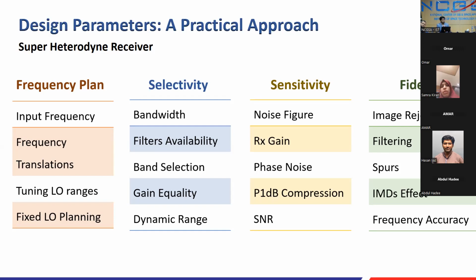How accurately it can produce depends upon the accuracy of the clock, the PLL, the programming, whether it is an integer-N type PLL or a fractional-N PLL, and how much accuracy you are getting out of that. So that comes into the frequency accuracy of the system you are offering. This was my learning gathered over the years: when we discuss with the customer and have a design approach, we should look into these things before finalizing any prototype or layout plan.